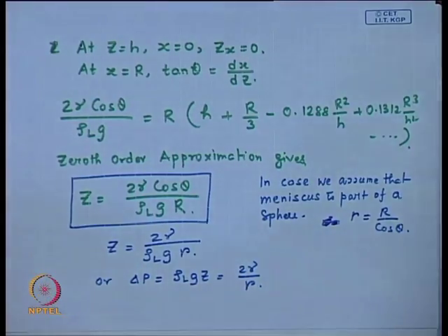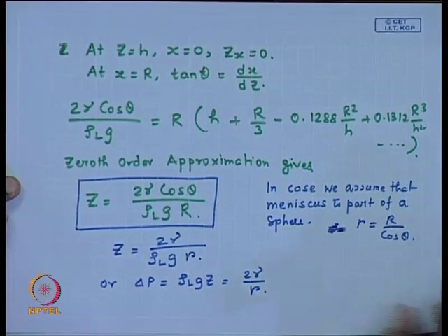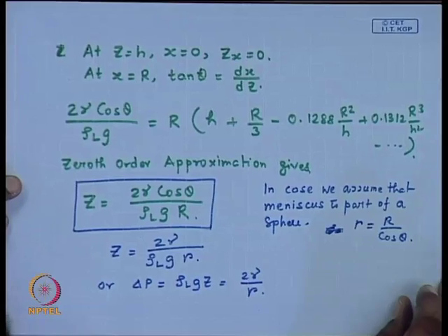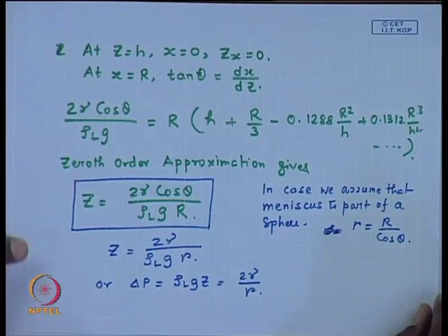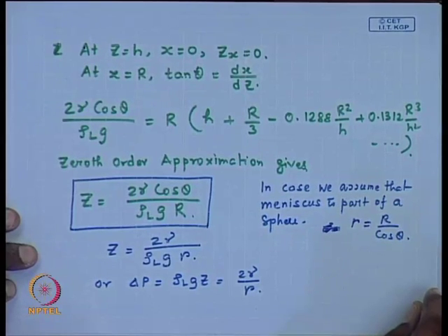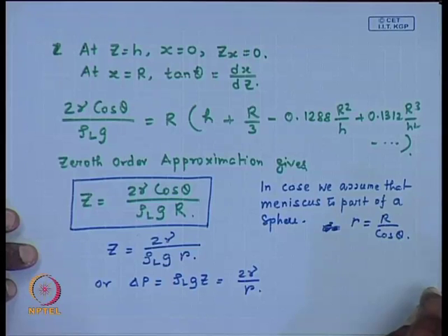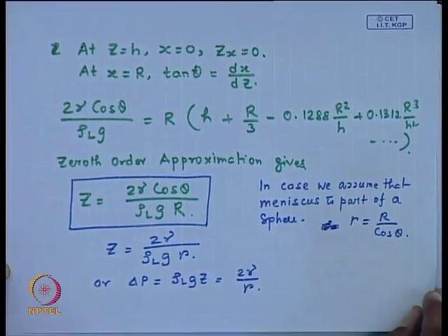Okay. So, this is fine, but from the standpoint of capillarity, the most important thing is to calculate the weight of total liquid within the column that can be sustained due to capillary motion. We all know that if you have tubes of different diameter of the same material, the narrower the tube diameter, the higher will the rise be. Essentially, based on the balance of the surface energies, the weight becomes constant. So, if you have a narrower tube diameter, you can see higher capillary rise.